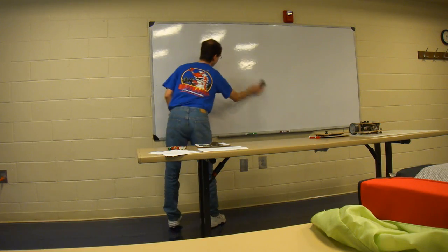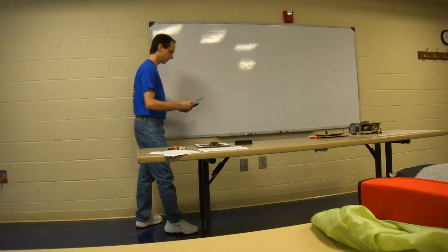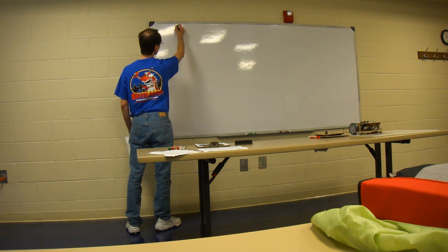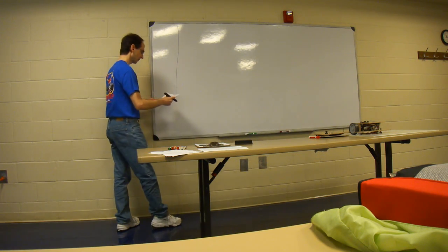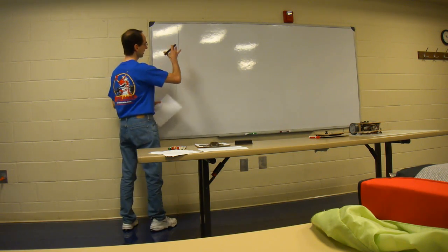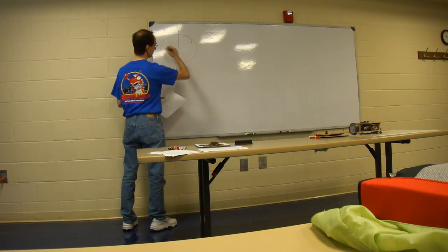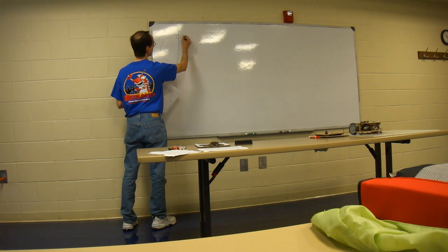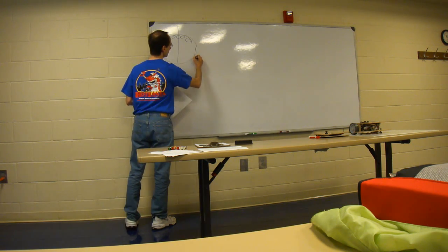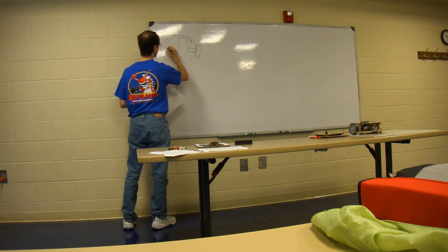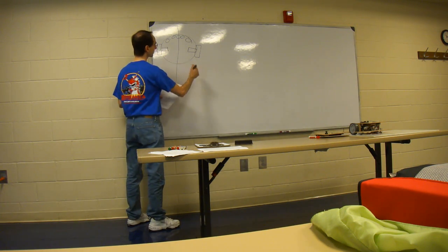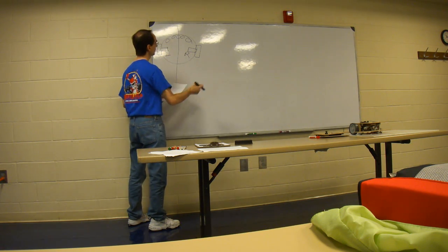All right. Now, let's use an example. I'm just going to use a typical example we use. We're going to do line following. So here's our line, and we're looking down at the line. And here's a typical robot, very similar to, say, the 3Pi. You've got 5 sensors, and you've got 2 wheels, and each wheel has a motor. Let's just say that's the right motor and the left motor.